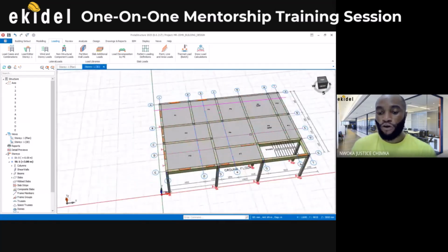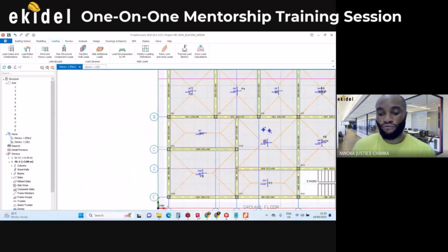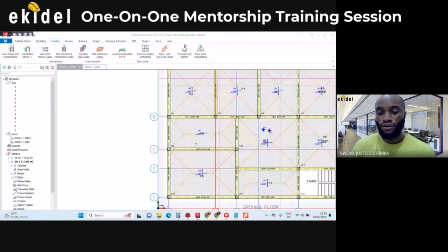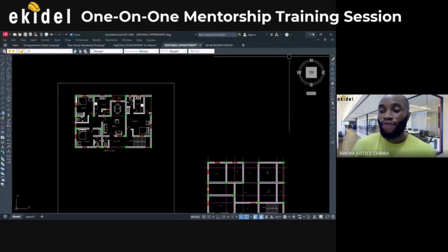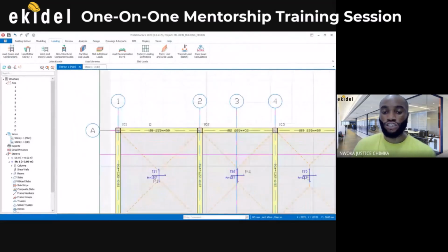Now, before I insert story, because right now we have just modeled this ground floor, which we have here. We have done the ground floor modeling. Now I need to insert the upper floor. But before I do that, there is something I used to do on my end of beams, which is to hinge it. Most people don't use to hinge.